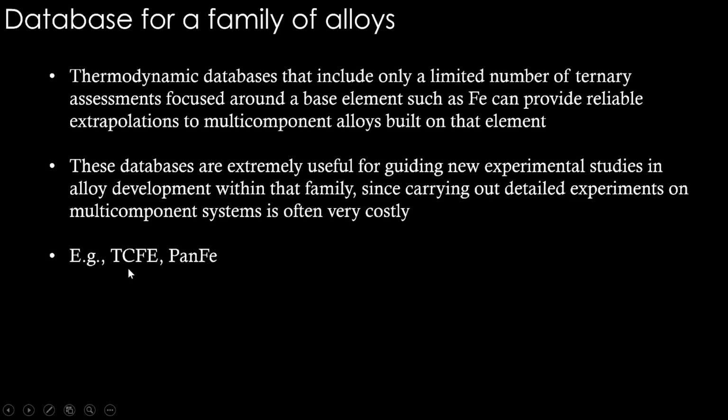One such database is TCFE, the Thermo-Calc iron database. This is used for developing new steels and so on. PanFe is from PanDat. And for nickel-based superalloys, there is the TCNI database. These are commercial, multi-component, internally consistent databases.